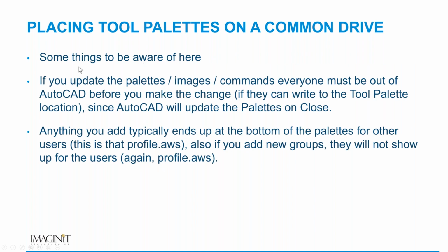So some things to be aware of when you're placing tool palettes on a common drive. If you update the palettes, images, commands, everyone has to be out of AutoCAD before you effect the change if they can write to the tool palette location, since AutoCAD will update the palettes on close of AutoCAD. So if you have multiple users and you're making changes to the palettes, yes, M leaders can be put on a palette. It's a command.